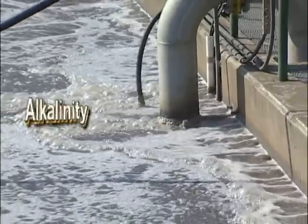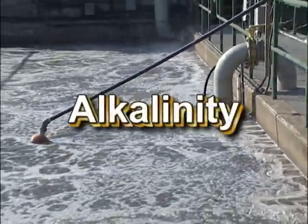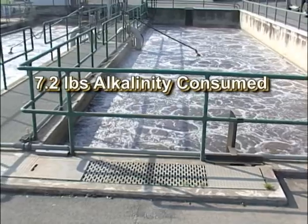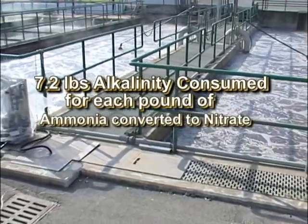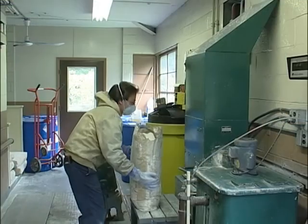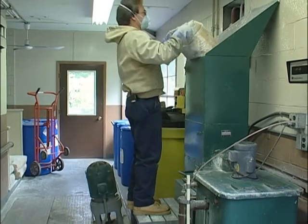Factor number 5, alkalinity. The process of nitrification consumes alkalinity. In theory, approximately 7.2 pounds of alkalinity is consumed for every pound of ammonia that is converted to nitrate. Insufficient alkalinity will bring a halt to the nitrification process. If the alkalinity is not present in sufficient quantity, you may need to add supplemental alkalinity in order to nitrify.